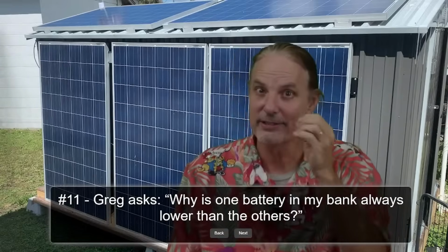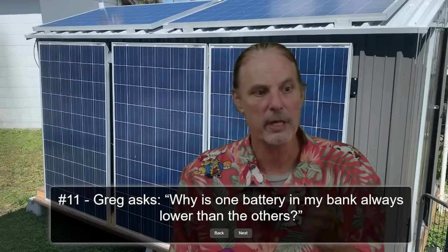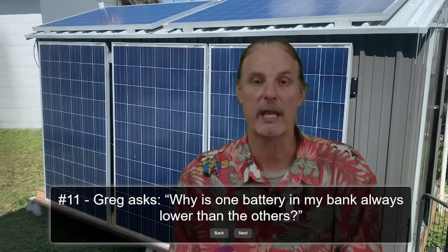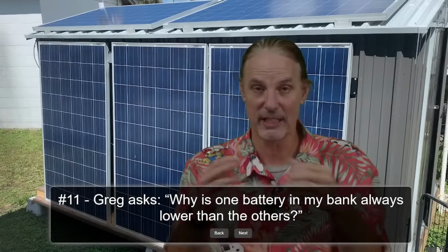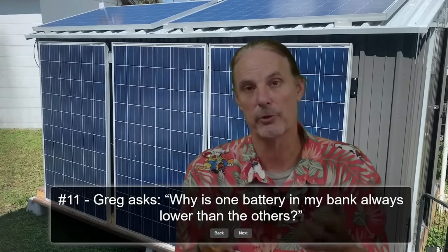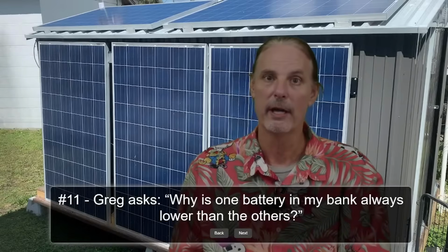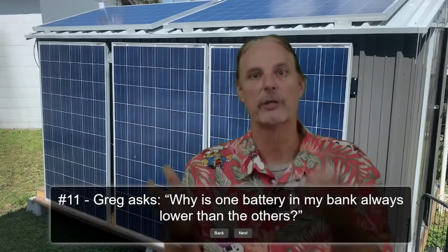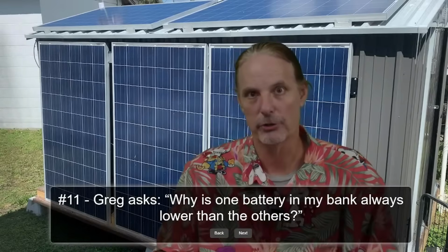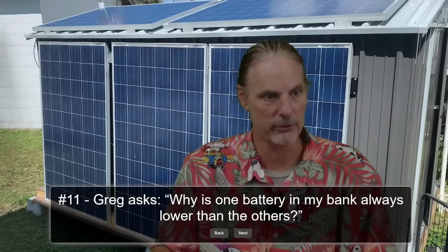There is, let's get as close as we can and let's calibrate the best we can, but you're going to have some that are lower than others. So you may have to calibrate certain batteries to get them more accurate so that they fall closer in line with the other ones, which is something you can do. But the best solution that I've come up with so far is to go to a universal calculator like a Victron shunt or something, where you're calculating the whole pool of batteries and not just individual batteries.